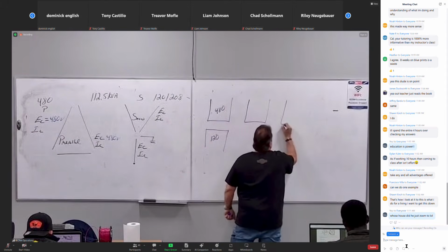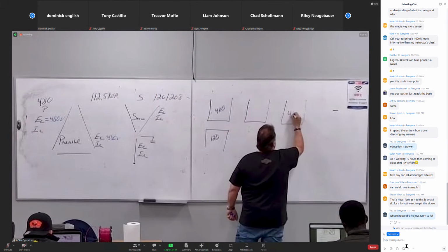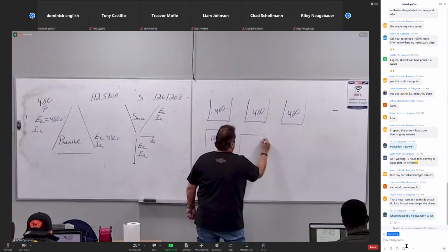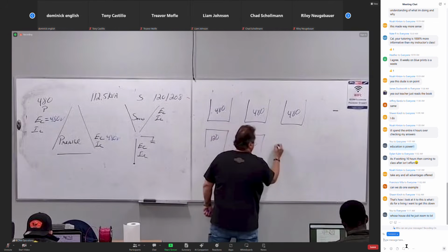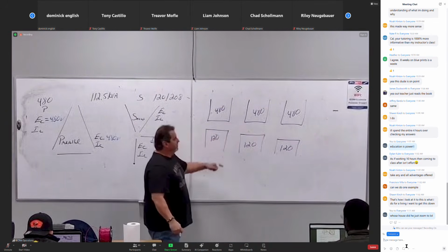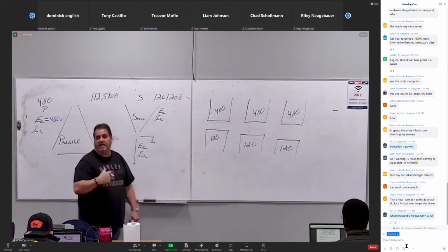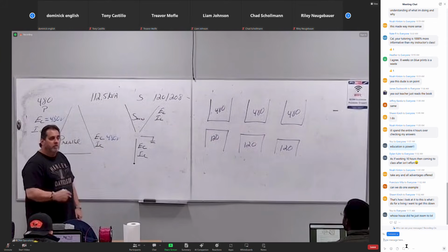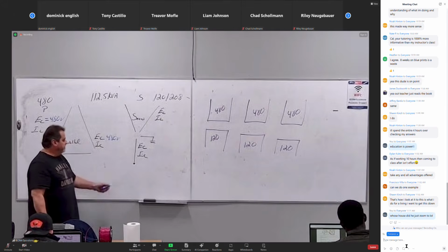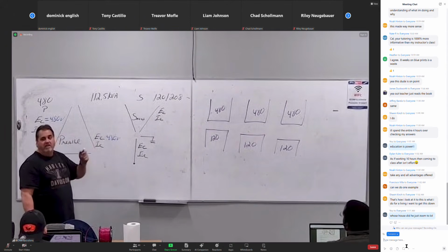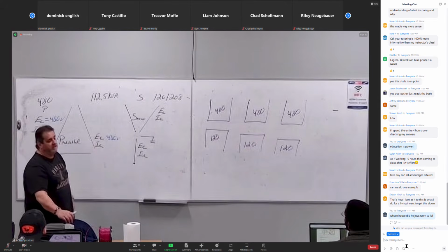And I have another coil right here, and every single 3-phase transformer that you've ever opened, that sits on the floor, you can look at it and there's 3 coils in it. You see in the one in the lab, there's 3 coils to it. There are 3 individual single-phase coils that we connect together to make 3-phase. So the turns ratio in a 3-phase transformer is between the coil voltage and the coil voltage, not line values. The only one that keeps it that way is the delta delta.